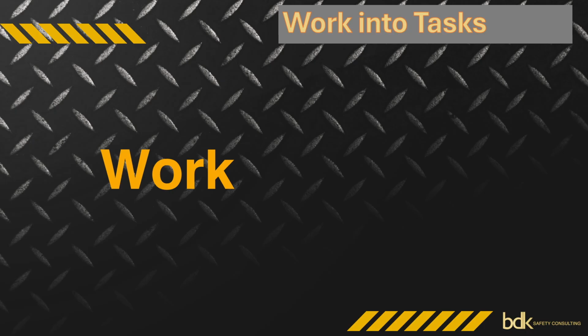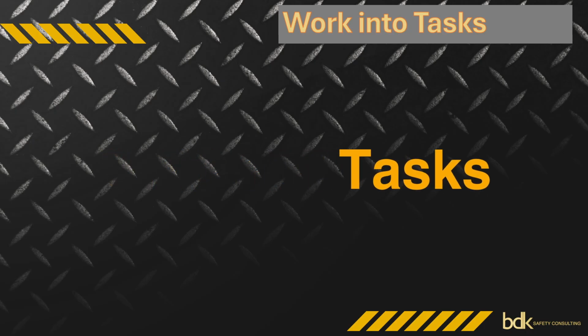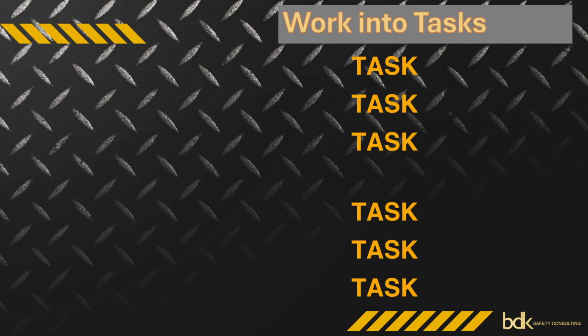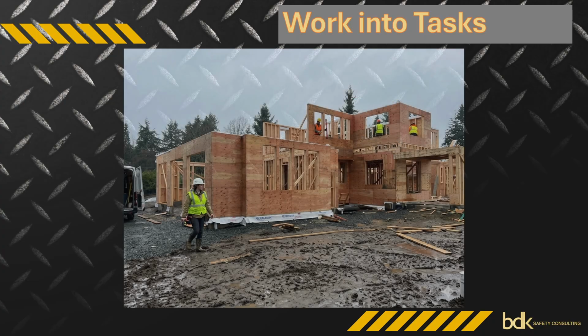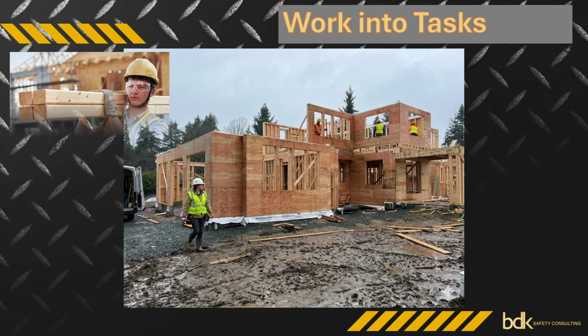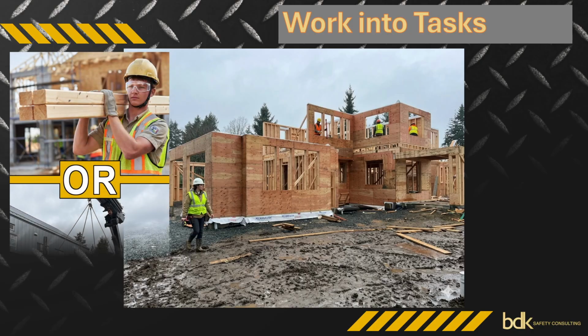With this in mind, let's look at how we can separate the work into tasks. We'll use the first example and break it into 4 tasks with one question aimed at identifying a possible hazard. The method would be the same for all the examples. Second floor framing starts today. Task 1, materials. How will the materials be delivered to the work zone and stored?